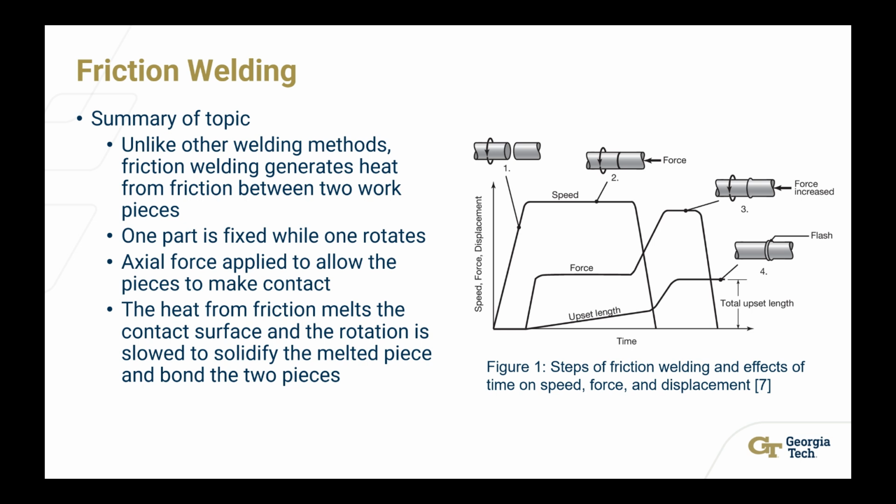The force is increased to remove the gaps between the two pieces, and the rotation is stopped to allow the contact point to solidify and join the two pieces together. This process allows the two materials to keep their material properties while fusing them together.